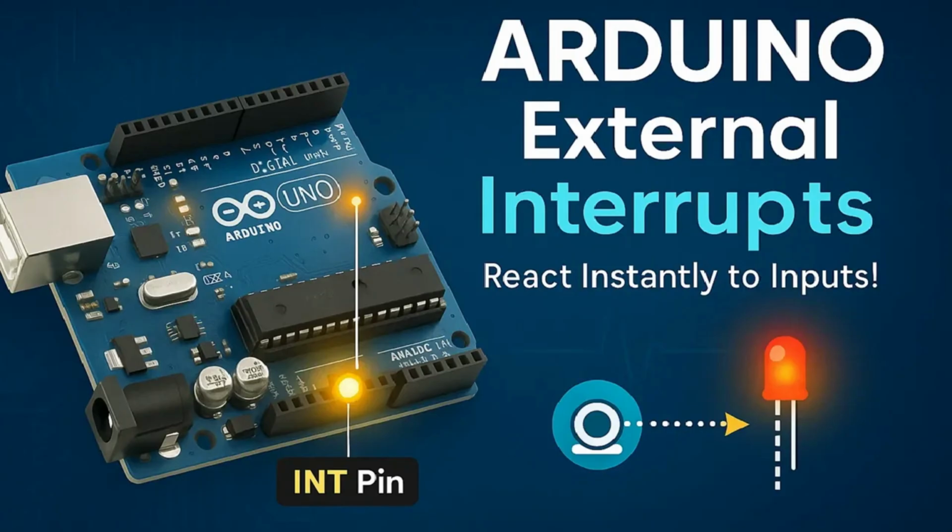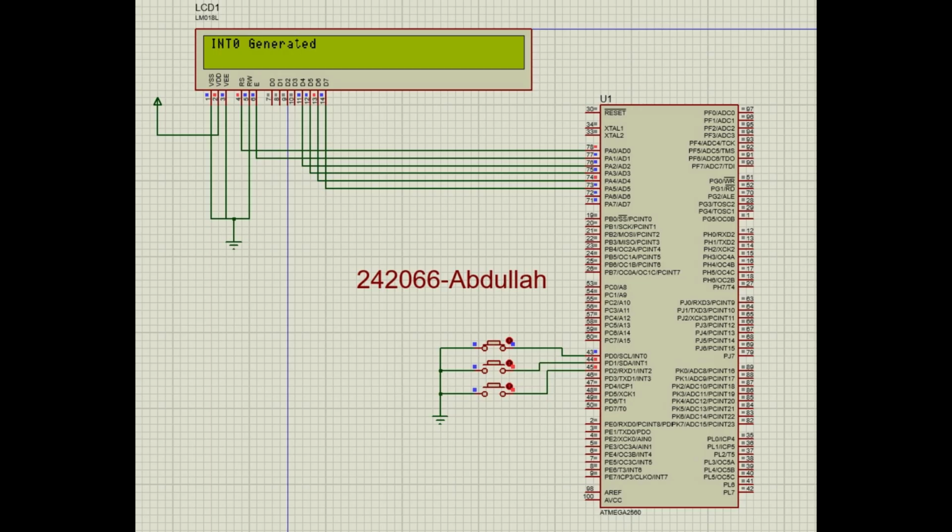The ATmega2560 has external interrupt pins: INT0 on PD0, INT1 on PD1 and INT2 on PD2. In this project, we will use all three, each one connected to a push button. Here is what we are building: three push buttons connected to INT0, INT1 and INT2. When you press a button, the corresponding ISR fires and displays which interrupt was triggered on the LCD. Simple but really useful for understanding how interrupts work in practice.